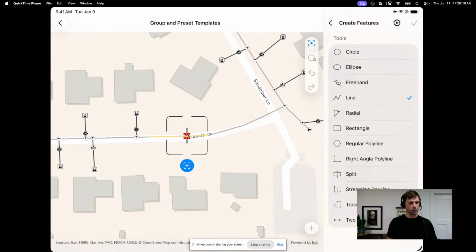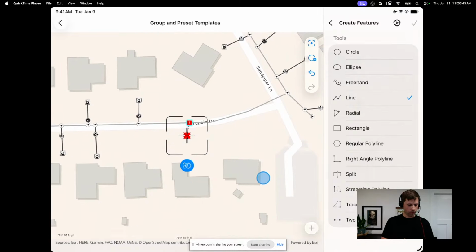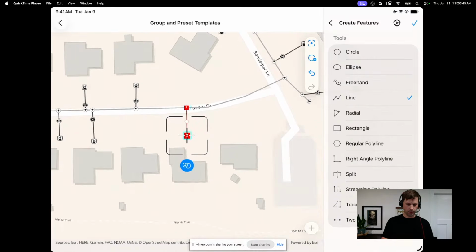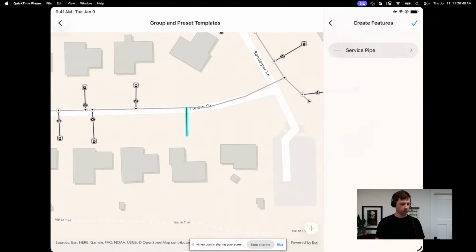The reticle is a geometry editing tool that we have created to help you see the edit that's happening without your finger. Like, you don't have any hands on the screen. I can see if I press that blue button, I know exactly where that point is going to drop right now. And I've also got snapping enabled. That's the gold feedback that you see on the screen. That gives me confidence that if I tap the button right now, it's actually going to snap to that line. So I'll drop 1 point, drop another, submit my edit, and I've created my feature.